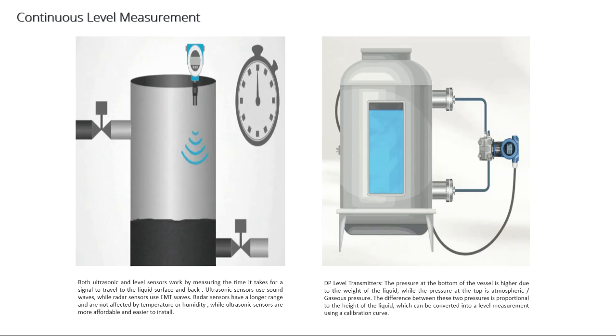The time of flight for this signal is inversely proportional to the level of liquid. If the level of liquid is higher, it will take less time for the sensor to detect. The time of flight will be less. And vice versa, if the level of liquid is lower, it will take more time to detect. These properties are scaled with one another, and by this technology, you can measure the level of liquid exactly.